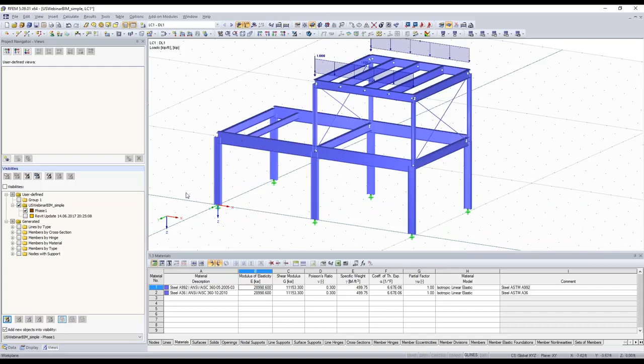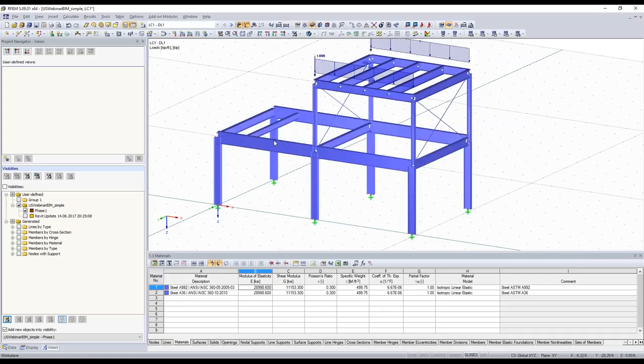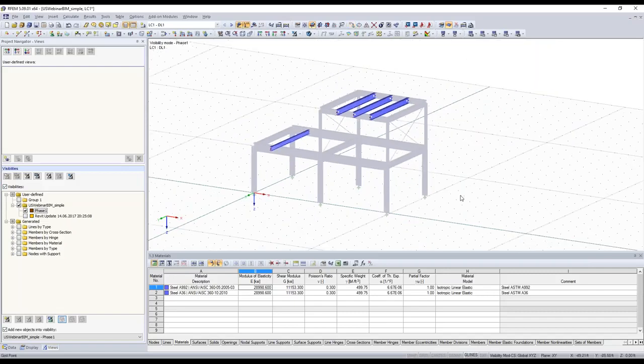Now I can either put all those changes in, if they're not automatically in there, I can also manually influence this. I can say, okay, the selected beam should be assigned into phase 1, and I say here equals redefine. Everything selected will be added. And now if I activate this visibility, then I have only this. So I can now update this, either select it,